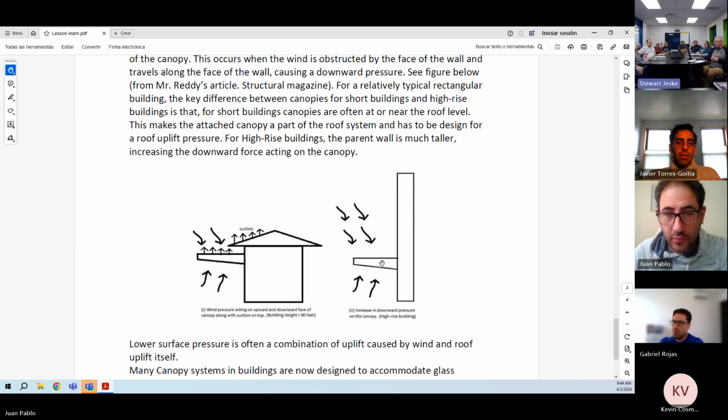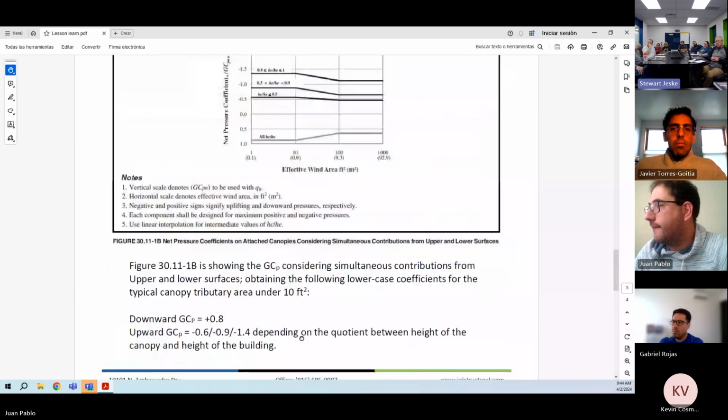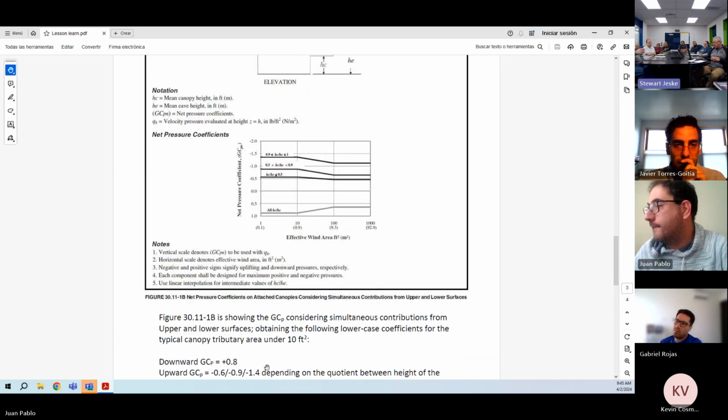Can you back up a little bit to where you get to the coefficient factors? Of course. Right in there, it looks like it could be possible to have 1.4 as a negative pressure coefficient, in combination with a positive underside coefficient of, is that 0.8?